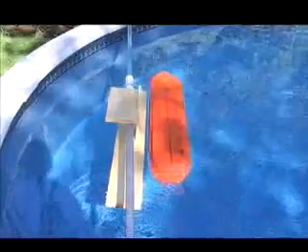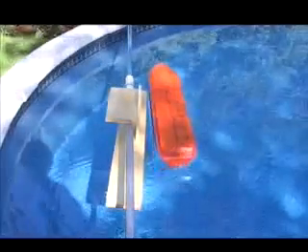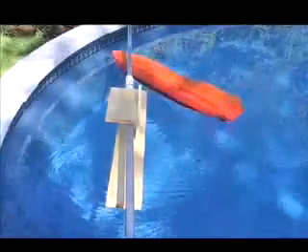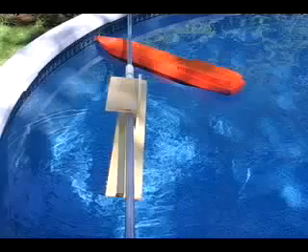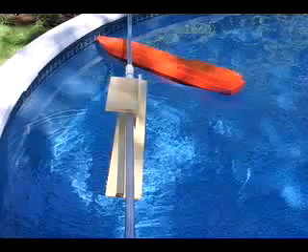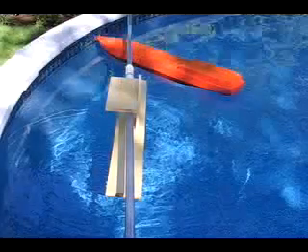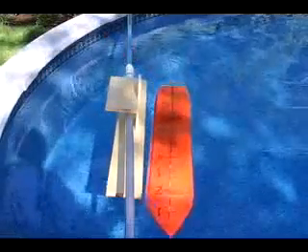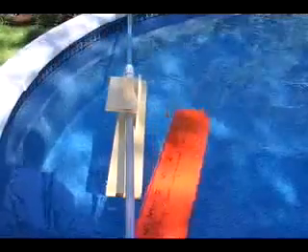Our small-scale model will turn around an open dock. When a third of the ship will be clear of the corner, the ship will kick ahead on a hard-to-port wheel. As we have all learned, the ship clears the dock since the pivot point is about 1/3 from the bow when moving ahead. Here is another example.